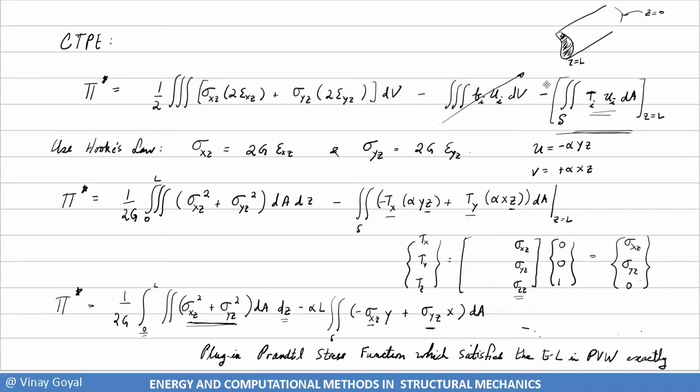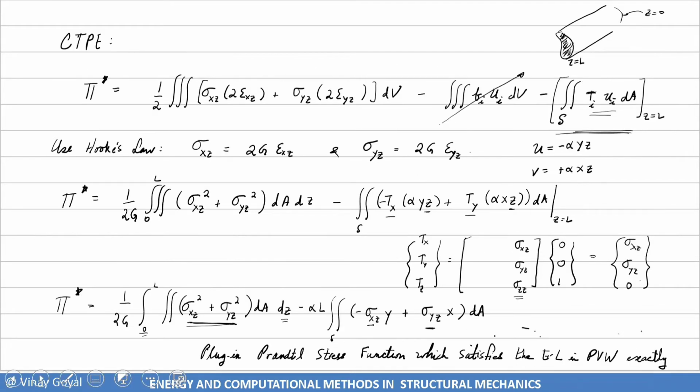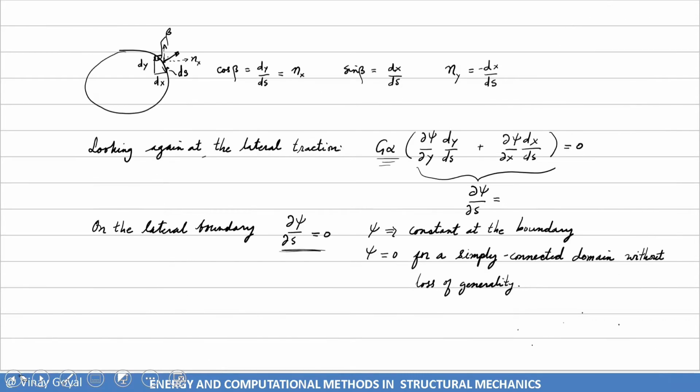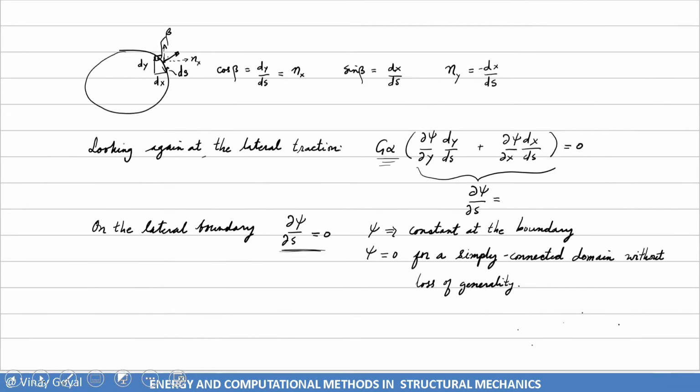So for the viewers, I want to make sure that it's understood. I made an error that was caught, and here I have a minus and a plus. If you recall, this term, sigma yz, was selected to be the minus. And why was it selected to be minus? You can see I have a minus there, so that this could go to 0. Otherwise, it would be plus, and you get twice G alpha. And I want the static equilibrium equation to be satisfied exactly. So that's why we did that.